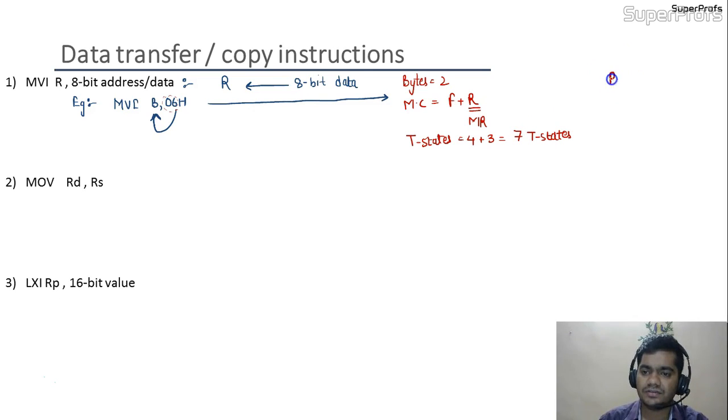And we should also comment on the signals of read, write and ALE. From this we can understand how many times the read signal would be activated. The read signal is activated whenever we are reading data from the memory. When we do the opcode fetch operation, we take the opcode from the memory, and when we read the content, that is 06, from the memory, we also use the read signal. So 2 times it would be activated.